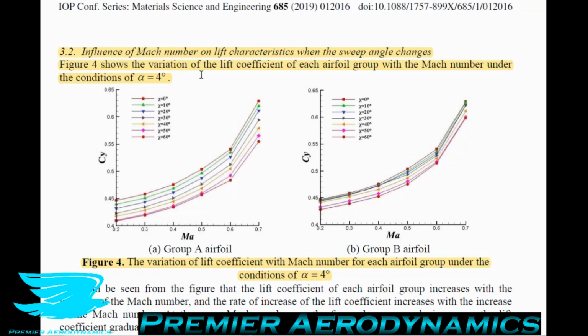allow the onset of what's called the critical Mach number. So it's not sonic flow. The critical Mach number is the number at which you need to be traveling for your object to experience sonic flow at some point over it. So for an airfoil, when the flow comes first, it hits the leading edge, then it travels over each side and it accelerates, particularly over the top, the suction side. When it accelerates, the speed obviously increases, so you're getting closer to the sound barrier than the leading edge is. So that means that you can actually have sonic flow on your airfoil, even though the free stream velocity is not a Mach number of 1. It can be lower than that. So that's what's called the critical Mach number.